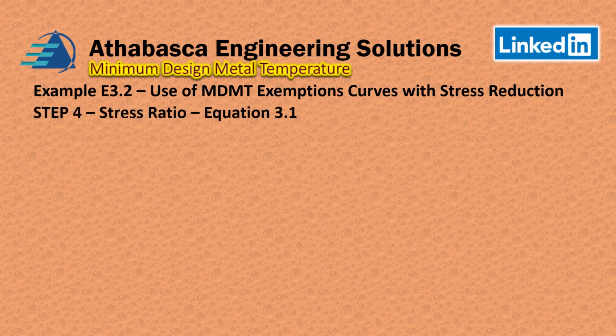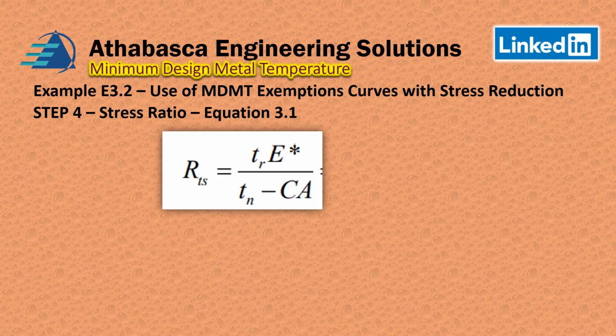So we'll continue on with step 4. We're going to go back to Equation 3.1, which is the ratio. So we've calculated the required thickness on the top, and we have to calculate this, which we'll talk about in a quick second. And we know our nominal thickness for materials. So for example, a 20-inch standard weight pipe will have a nominal thickness of 0.375 inches, and so that's what you have available.